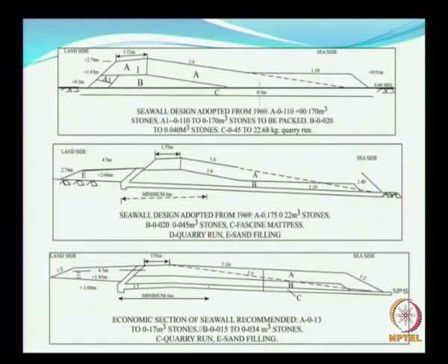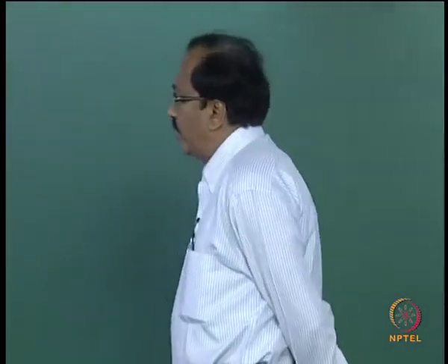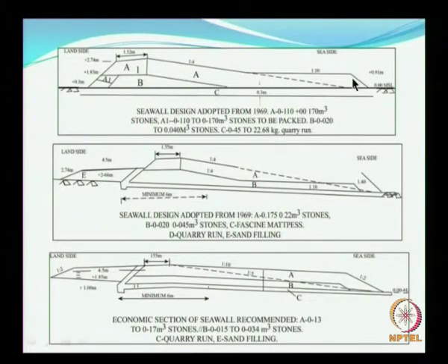So these were some of the standardizations of seawalls. All along the Indian coast, most of the structures that were adopted for protecting the coast were seawalls, in most of the locations, and it was the Kerala government which came up with the standardization of its seawalls. So the idea is very good. You look at the concept wherein you have a front slope of 1:10, a very mild slope, and then you have a steep slope of 1:4.